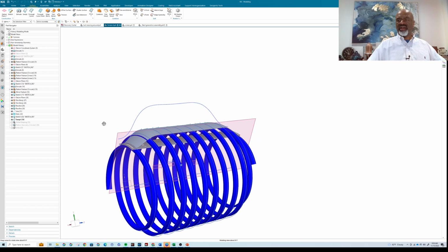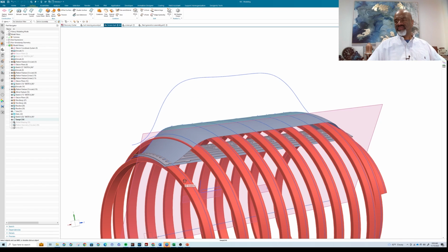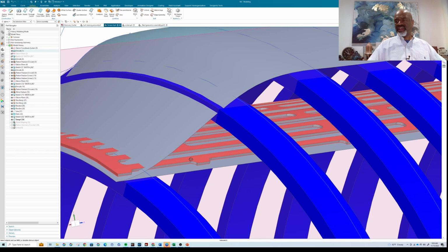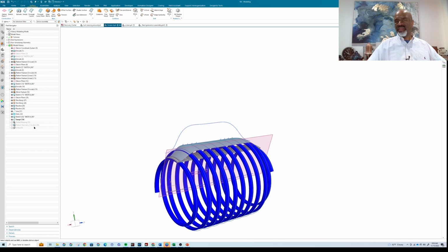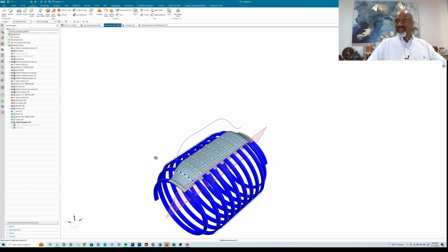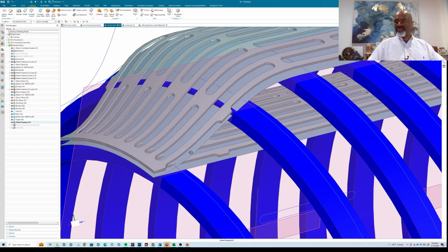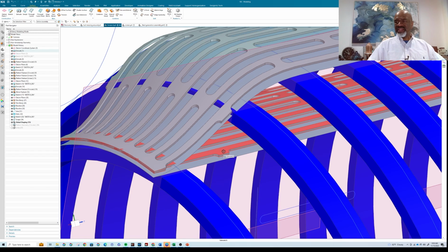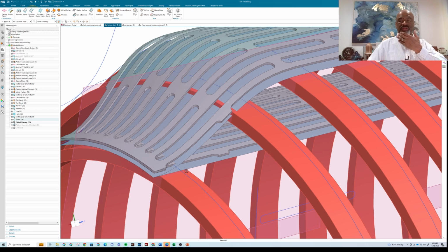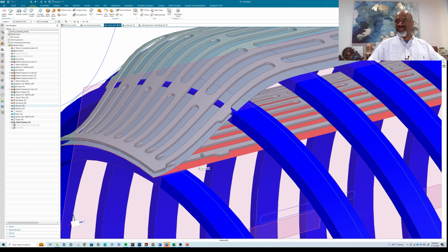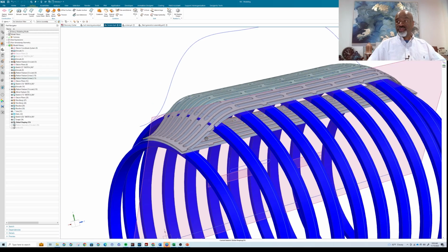So I used the forced direction command and did that, so that's great. Then I had the helix. I had the section of the screen, and so the next thing I did was a global shaping, and I did the global shaping via Surface. Global shaping is an amazing command. I use it a lot, and as you can see, what the global shaping does is it takes my original screen and it imposes the same deformation on it that happens from this flat surface to this curved surface.